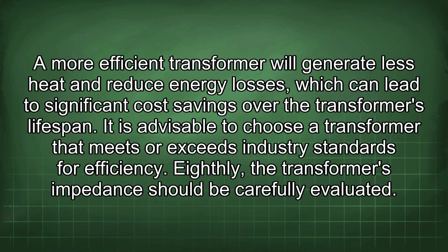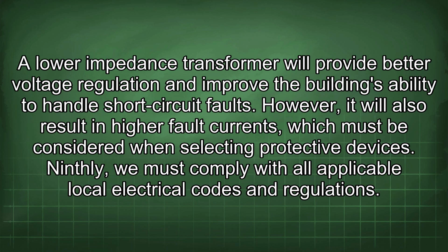Eighthly, the transformer's impedance should be carefully evaluated. A lower impedance transformer will provide better voltage regulation and improve the building's ability to handle short-circuit faults. However, it will also result in higher fault currents, which must be considered when selecting protective devices.